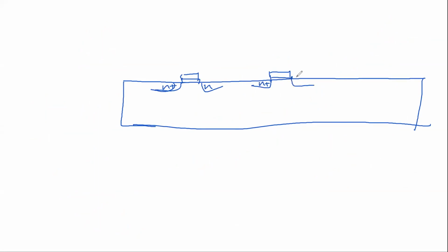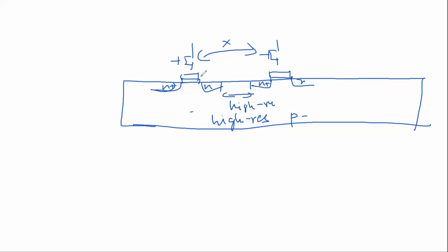These are two transistors, right? There's a MOS here, there is a MOS here. You don't want them to talk to each other unless you want to, which means this body of material you want it highly resistive, and that's why you use a P minus, because the area is fixed, right? You want the minimum area between these two and the highest resistance between these two, because you don't want these two circuits to be shorted by a resistor here, a short resistor.